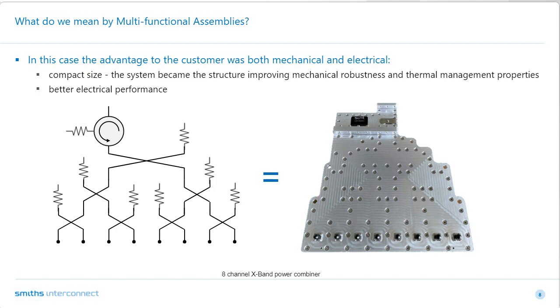So we've got 8 times 20 watts going into the isolator, and you've got approximately 160 watts coming out. So here we ticked the boxes of improved insertion loss, lower mass, a more robust structure, and it added this intangible benefit. And I guess another way of looking at it is, had you made this component from just a bunch of different parts, the tolerancing on the components would be pretty severe, and it would probably have just cost more.